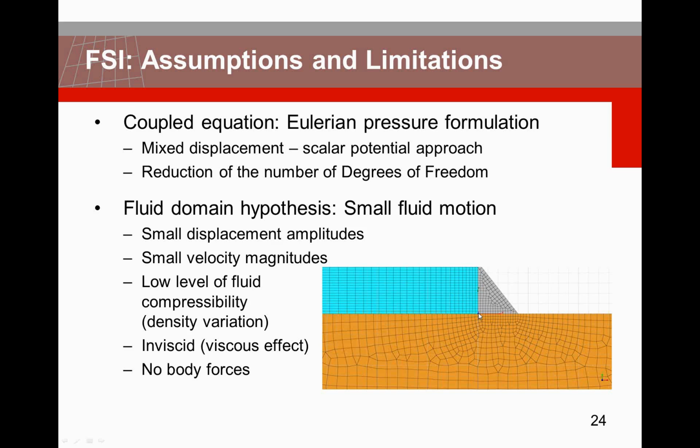There is no physical interaction there, but there can be appropriate boundary conditions at the fluid and at the structural domain to account for that. In this case, the only part where the real fluid structure interaction is taking place is between the reservoir and this vertical side of the dam.